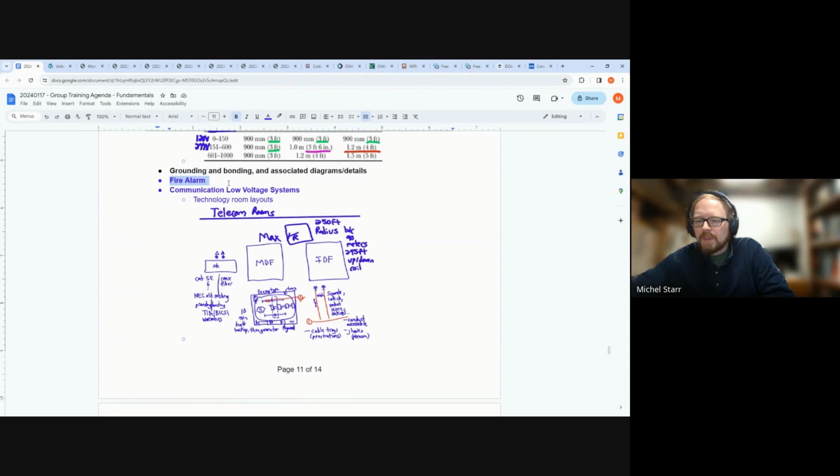Fire alarm systems may or may not be needed for buildings. There's initiating devices and audio and visual appliances. So you need to locate where pull stations are, such as at exits, and it's within a distance from that exit that it's required to be. Where smoke detection goes really starts to be the building code. So NFPA 72 is specifically for fire alarm, that's not the building code, but the building code itself depends on the occupancy, something that you really have to look at heavily for fire alarm to start off the conversation of what is the appropriate design.